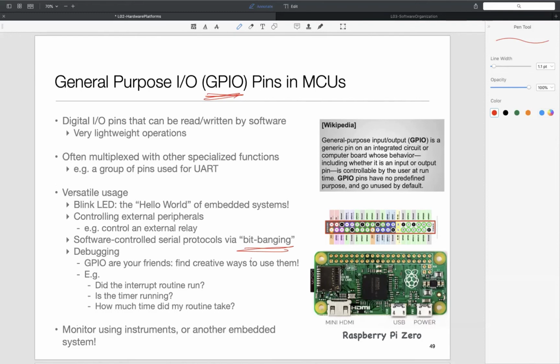So nowadays, for fairly cheap, you can buy hardware which connects to the USB port of your computer, and then much like an oscilloscope, it can monitor the I/O of your devices. In fact, one of the things you can also imagine doing is getting a second Arduino and using that second Arduino to monitor your main Arduino, for example, right? If you're outputting the signal, that other Arduino can act as the monitor and controller for it. So I often do that.